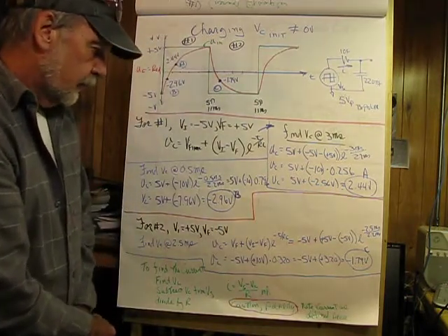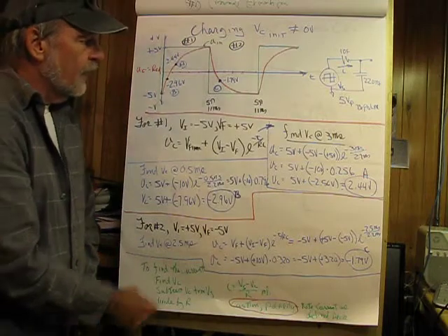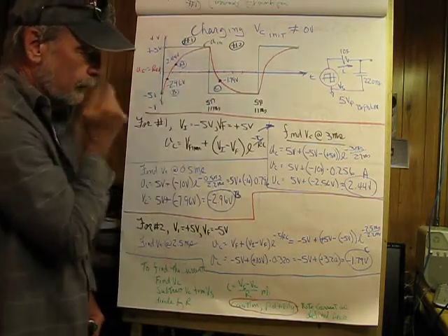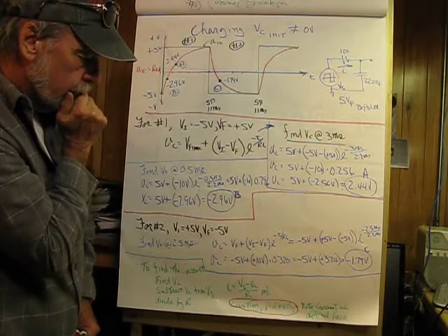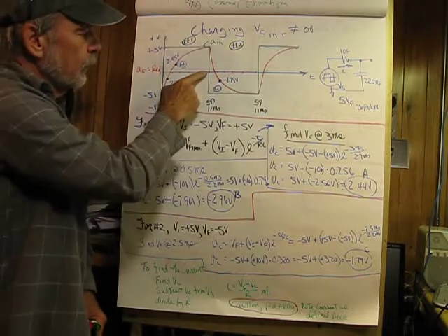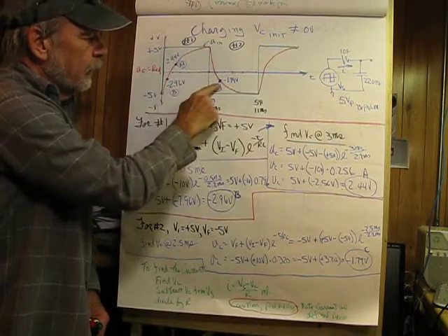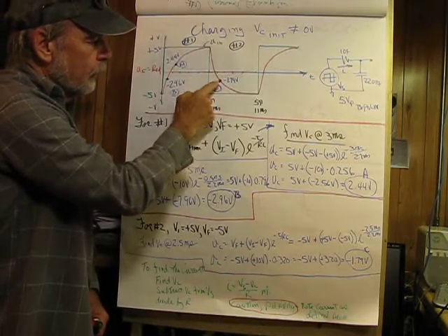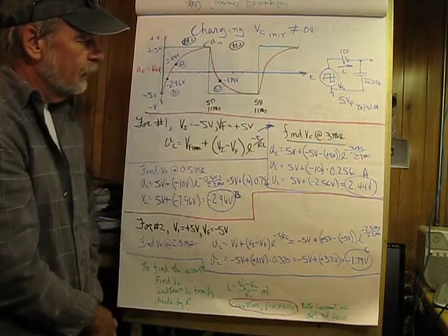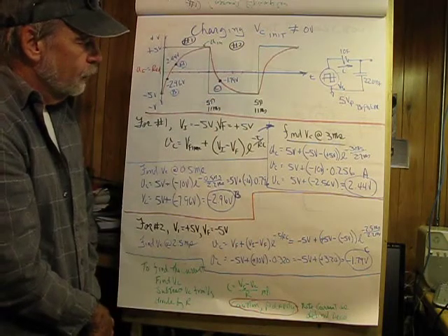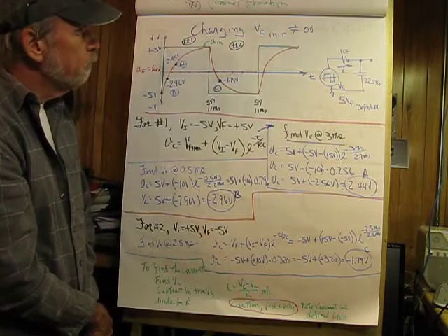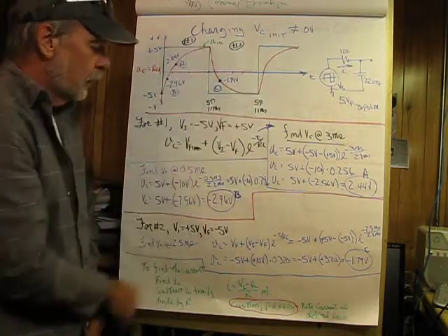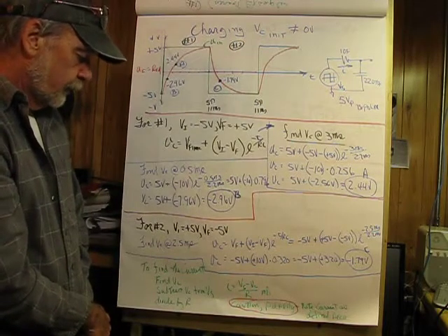So at the time of 2.5 milliseconds, relative to the beginning here, we see that we're down here, and this would be 3 milliseconds, at negative 1.79 volts. So this would be charging starting out at plus 5 volts with a terminal voltage of negative 5 volts.